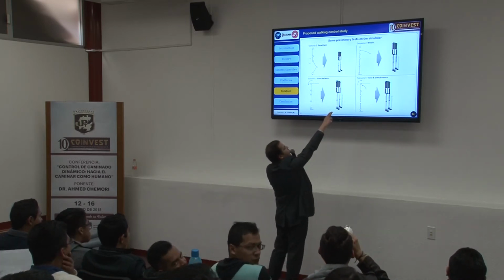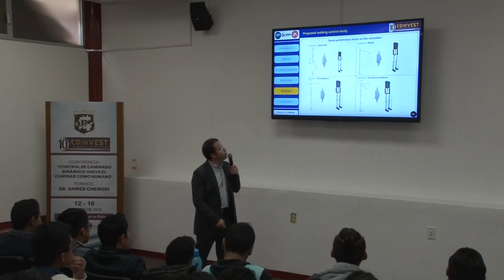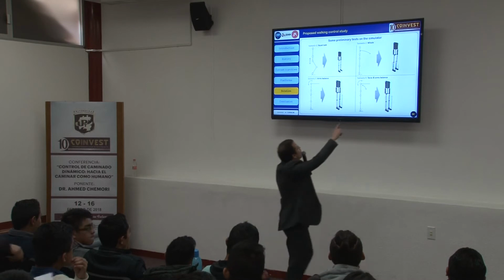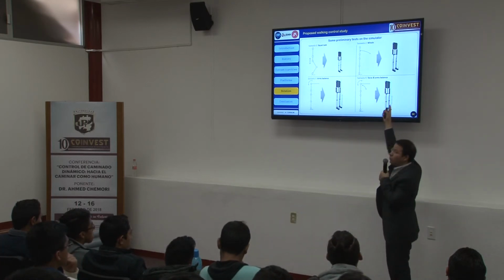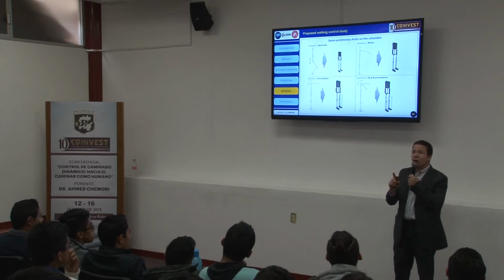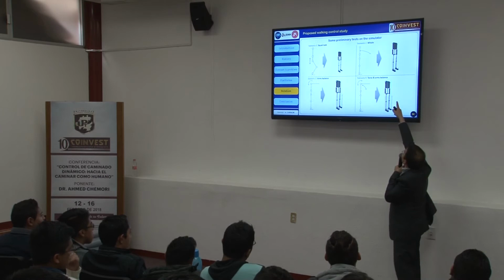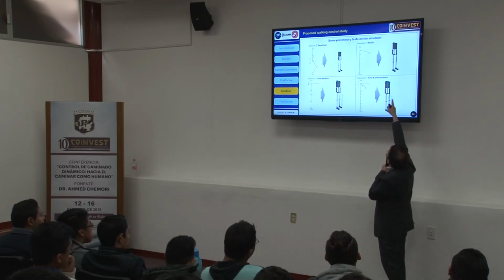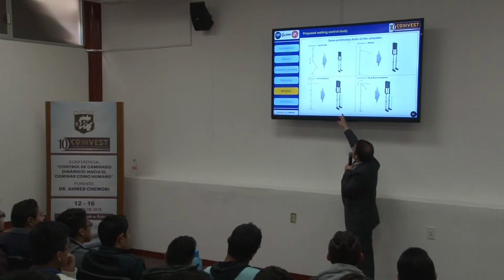Now, the second video here, we can see the whole body motion. We try to do this balance. And also, as you can see here, the change of the contact forces. The point which is in the middle is the position of the ZMP. It's the resultant force regarding the Z-axis. And as you can see, if the forces are modified, this position will move. Now, let's see the third video.